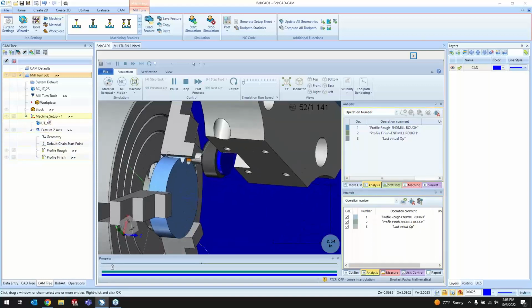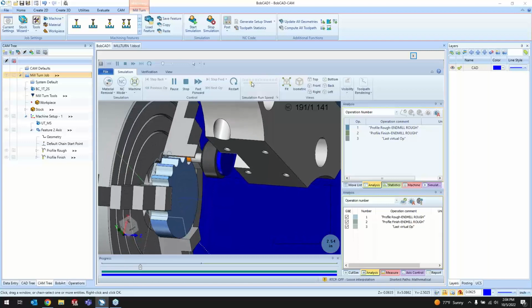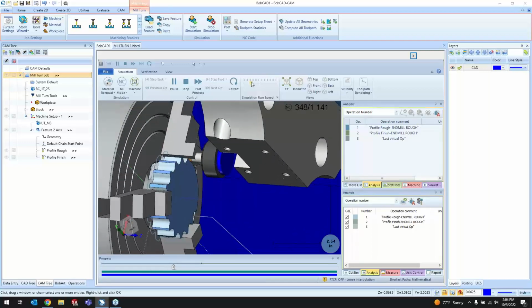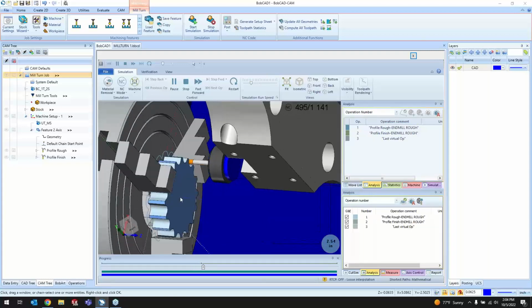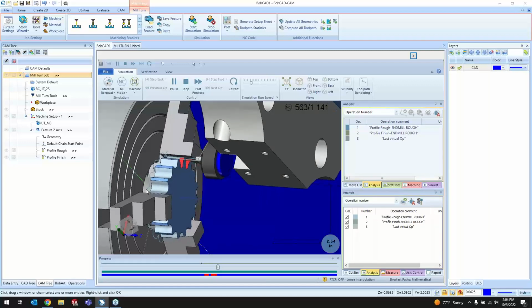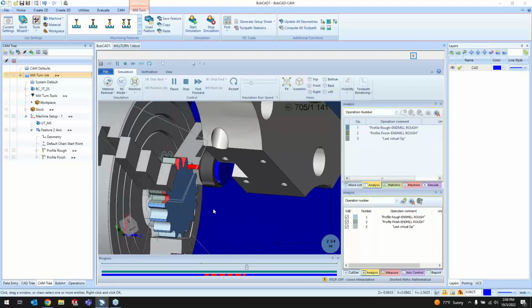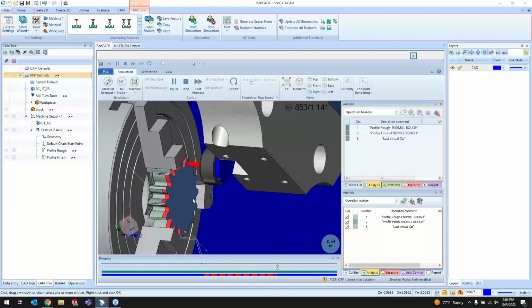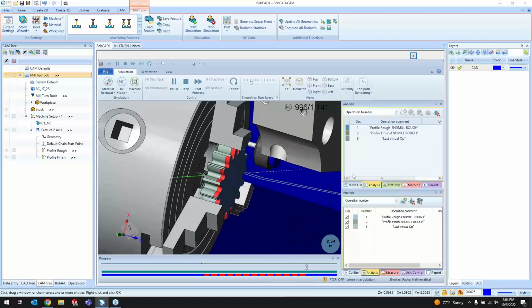But with that work offset in X, Y, and Z in the machine setup, it does not change anything in the G code. It just changes the simulation here. It changes the stock location of the simulation, where the XYZ 0 location right here is not at 0 at the top of the spindle here. I can move it outward in Z so that it doesn't have any collision. And then this red also is showing a collision.